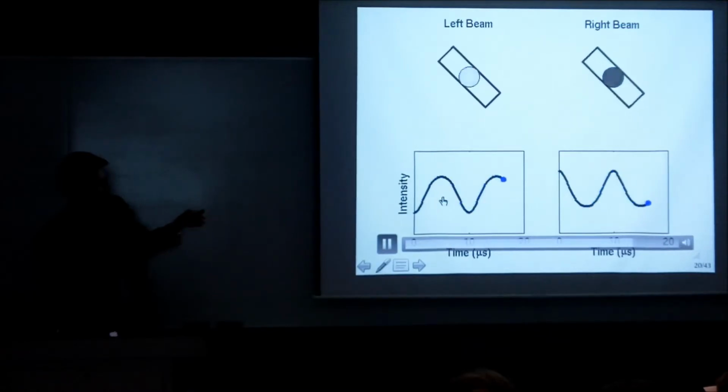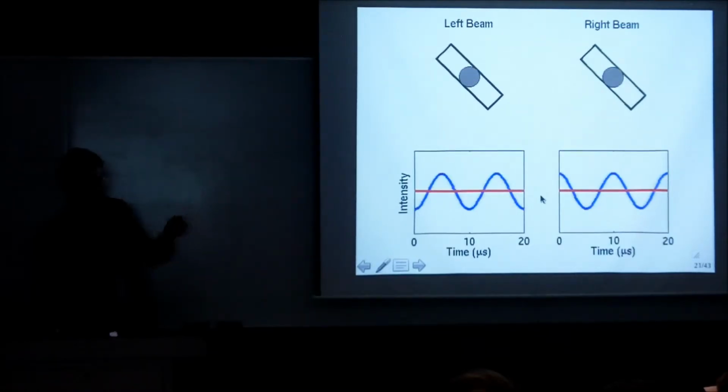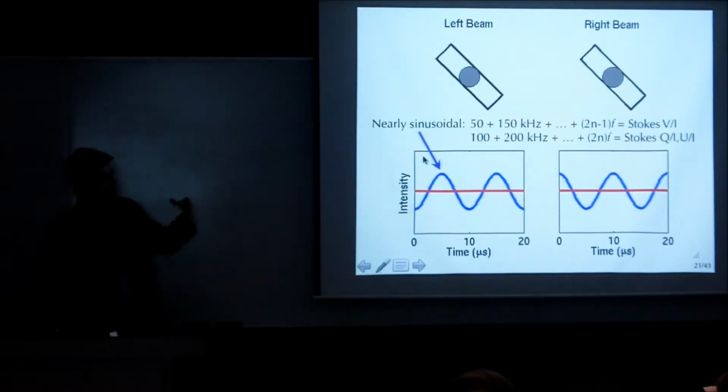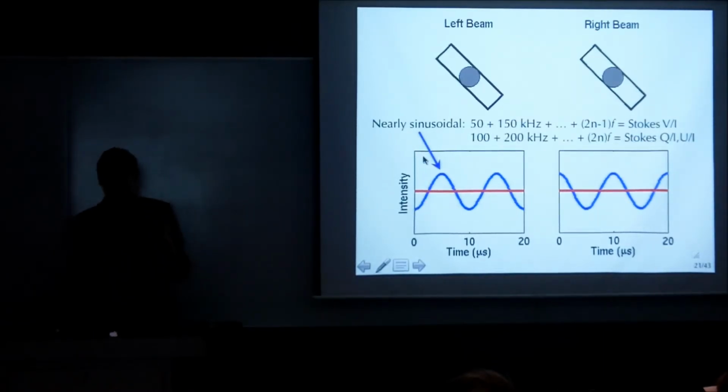So you see the sinusoid-like modulation that's out of phase between the two detectors. That's by design, so you recover all the light. The sum is constant, maybe not zero. You can see that this sinusoid is made up of many frequencies: the odd harmonics of the resonant frequency of this bar of fused silica, which is 50 kilohertz.